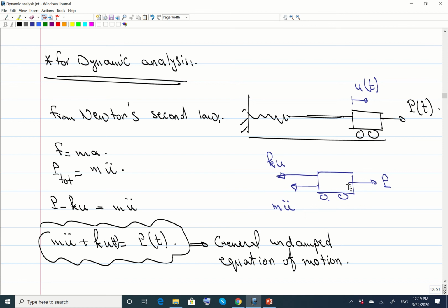So here, when you apply a force here, P, that is changing so rapidly, U is going to change with a high acceleration. This object will move with a high acceleration U. There will be some inertia force that is a function of the acceleration, U double dot. So what's double dot here? It's d2u by dt squared. Okay, let me hide this here. So m d2u by dt squared. Okay, this is called the inertia force.